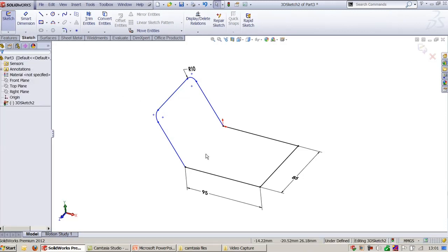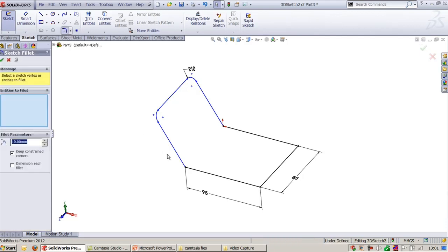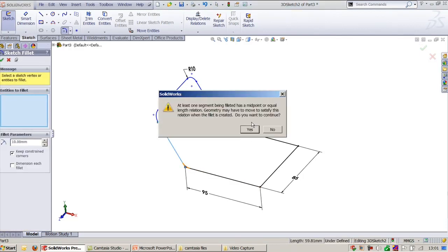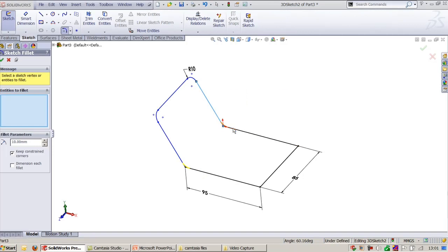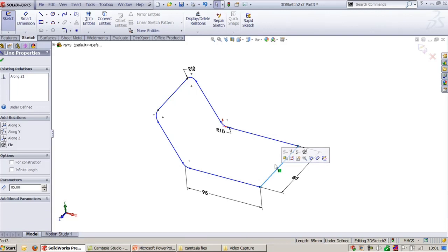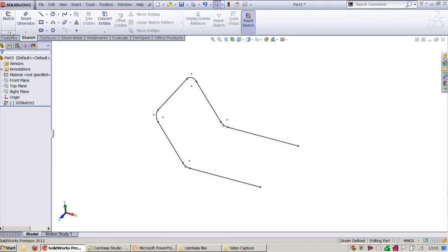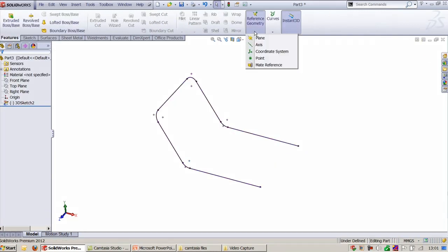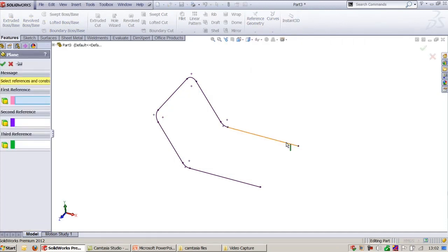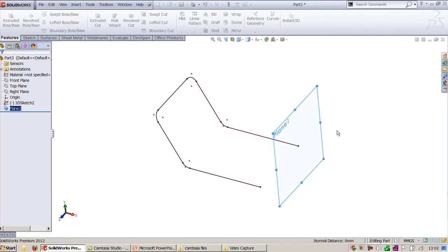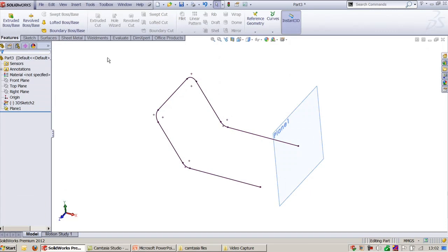This is what the functionality. But let's look into one more advantage. When you create this 3D sketch, it will act as a single entity. Now what I will do, I'll remove this line segment, and I'll remove this line segment. And now if I go to creating a sweep feature, I have this one single entity, and I'll create